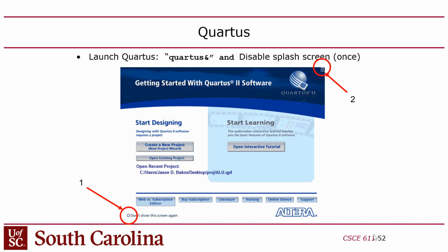Trust me, that's awful. If you ever did breadboard stuff, or even did a chip layout, by the way, which is also terrible. That's when you actually draw polygons that you send to a chip fabrication place to actually fabricate an ASIC. Yeah, it's awful. When I was in grad school, I used to spend months just routing the pad frame for a chip, just drawing the polygons to create the I/O pads and making sure that all the design rules are met by filling in all the empty spaces with metal stacks and all that stuff.